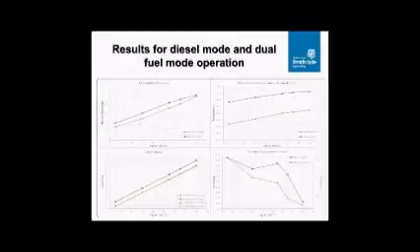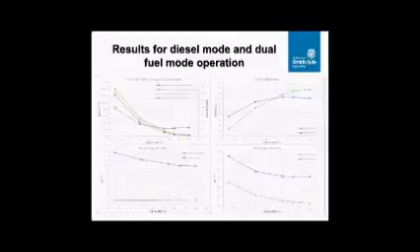The dual-fuel mode is more efficient than diesel mode for loads above 70%. However, less efficient operation was observed in the lower load region. The carbon oxide emissions in the dual-fuel mode were reduced by 25% on average due to the natural gas's low carbon to hydrogen ratio. A larger reduction is seen in the high load region, where the efficiency is higher than that in diesel mode.